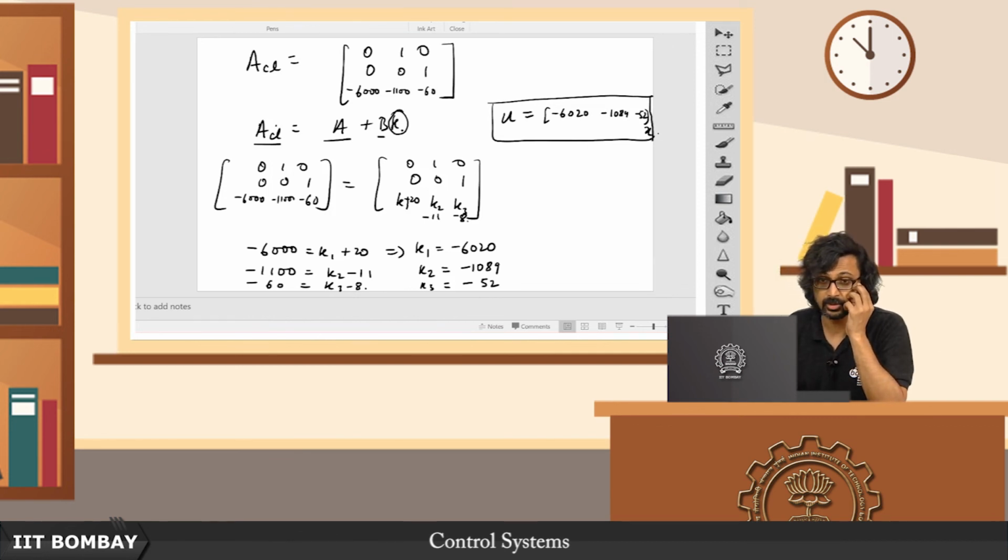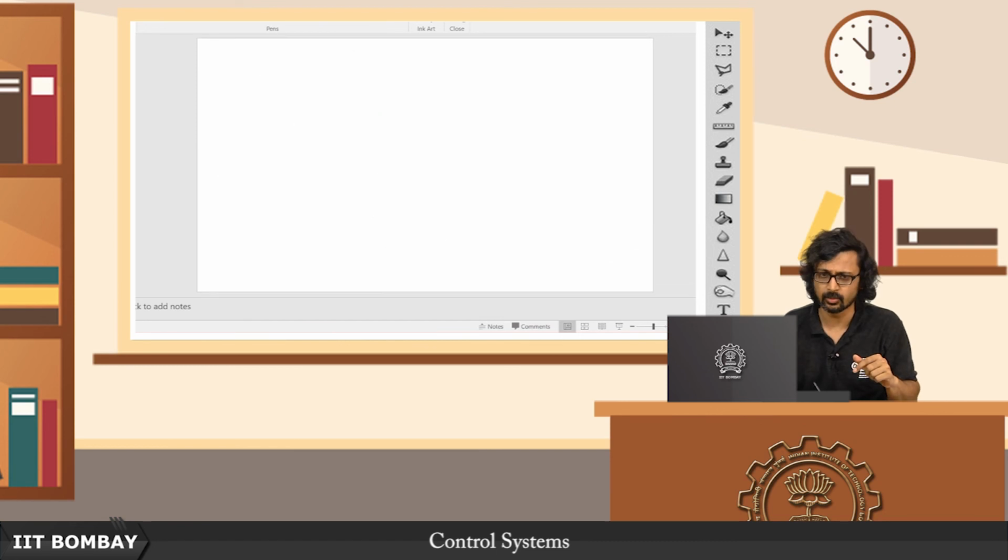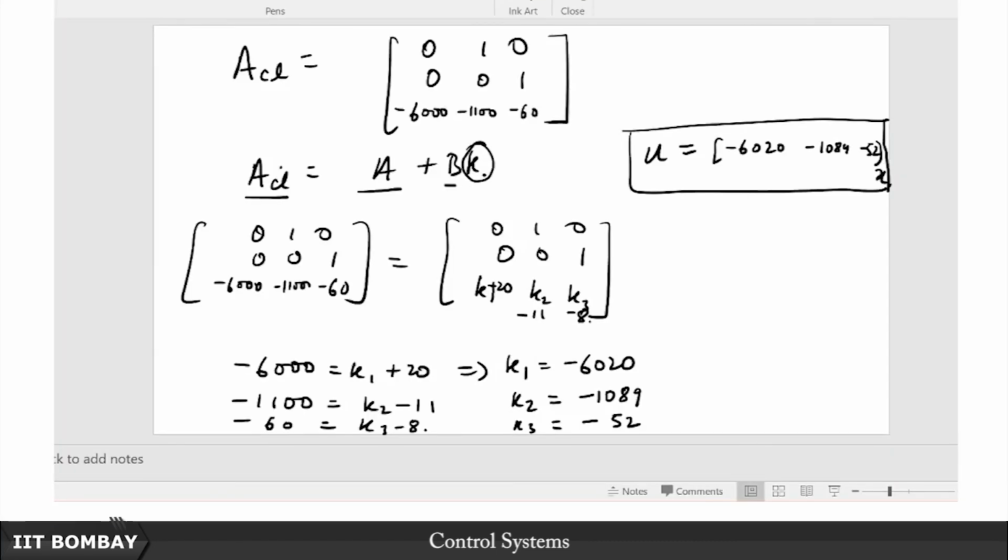What if this was not given in the controller canonical form, what if it was realized in some other form? Here I had the choice of realizing it in any form, so I chose the phase variable canonical form. To reiterate, there are two methods. One, you could have gone from that arbitrary form of realization to the controller canonical form, gotten these gains, and then through the similarity transformation, that T inverse I just showed you, which is basically CC times C inverse, like we derived a few classes back, got back the gain in terms of the original states.